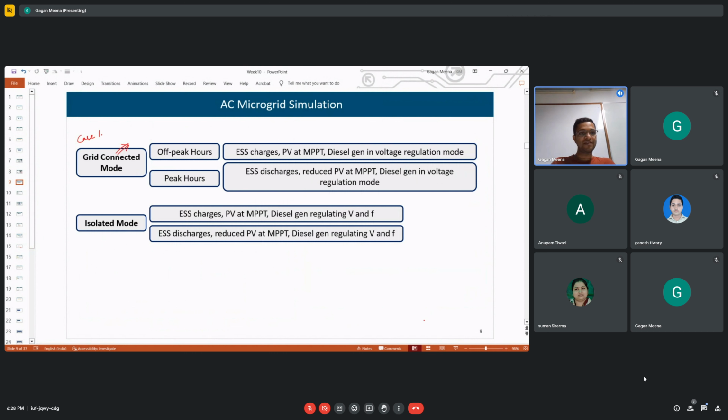Their rotation is anti-clockwise, opposite to the positive sequence. Negative sequence will only happen when there is some fault? No. Otherwise, why is negative sequence there during a fault? Because there is unbalance. Suppose there is an LG fault, a fault from one phase to ground.